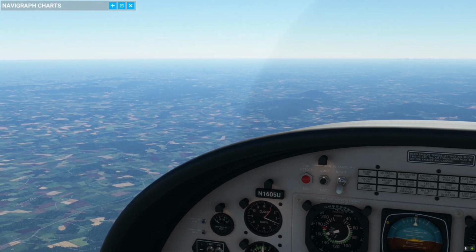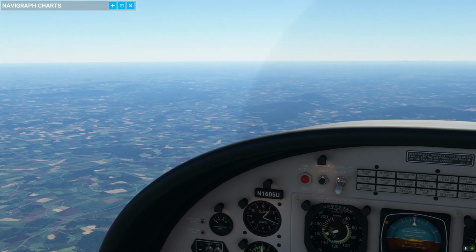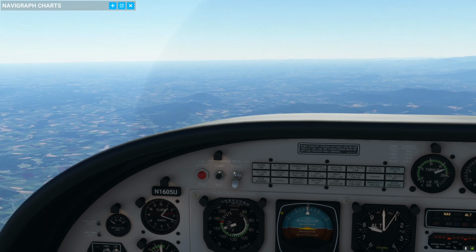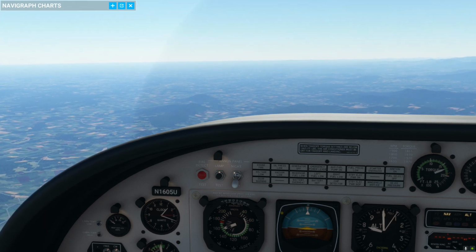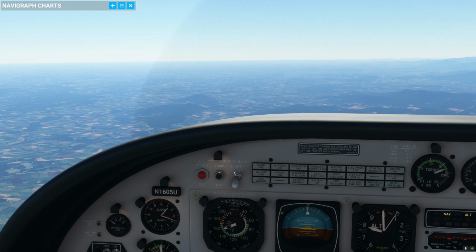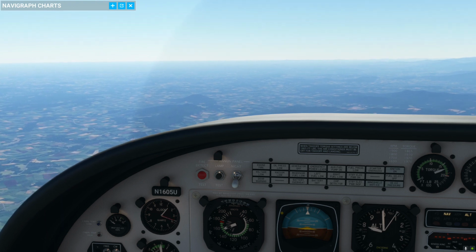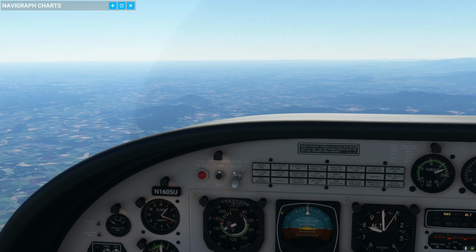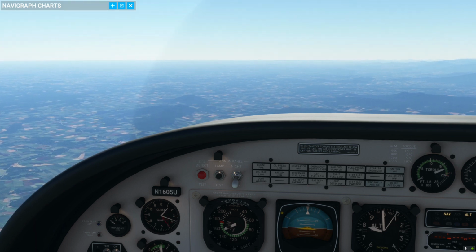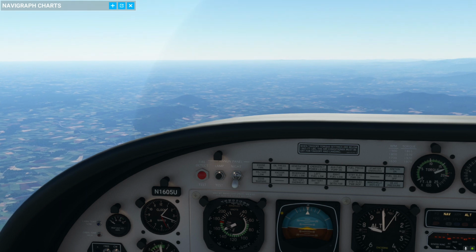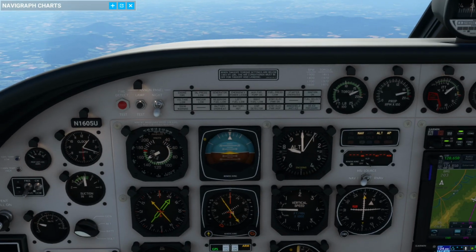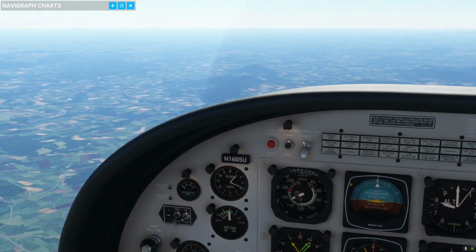Normal landing distance is 1,836 feet. But you can do a short field with an engine out, kind of will be anyway because you're not going to have extra power. Just don't come in hot, full flaps. Try to be as slow as possible right before touching down and keep the nose wheel up when you're on a field or grass because you don't know how mushy it is.